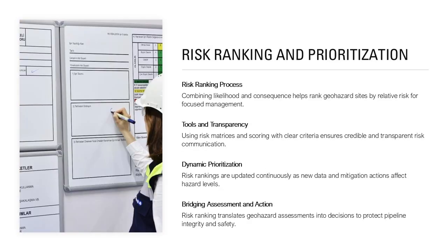Risk ranking and prioritization translate geohazard assessments into actionable decisions. By combining likelihood and consequence evaluations, engineers can rank geohazard sites or segments according to relative risk. This process supports efficient allocation of resources for monitoring, mitigation, and further investigation.